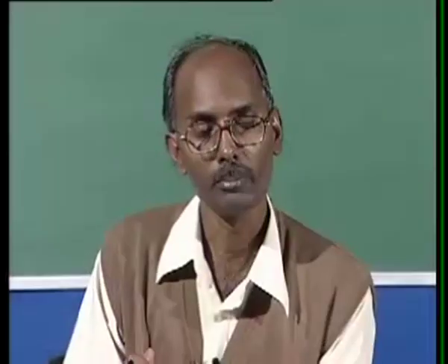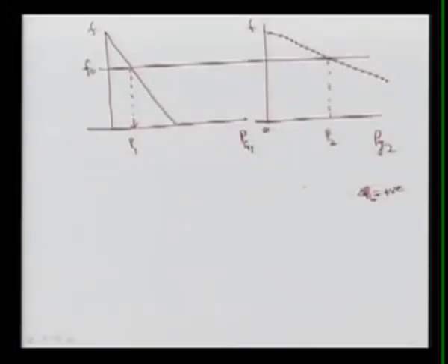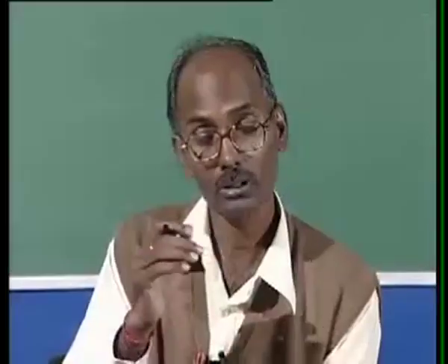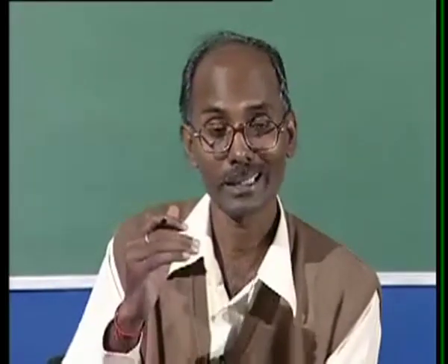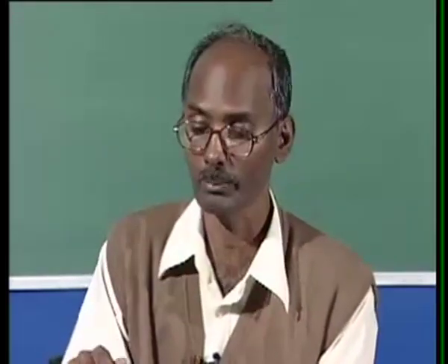What will happen? Now that load must be shared by these two generators. They must share in such a fashion that the steady state frequency is again constant and fixed, and it will of course be lower than before because the power is increased.